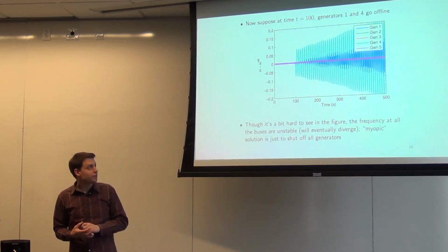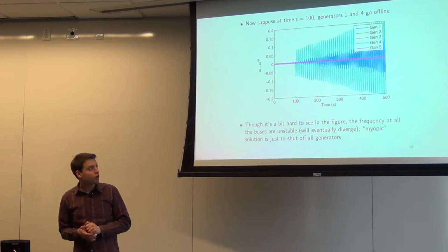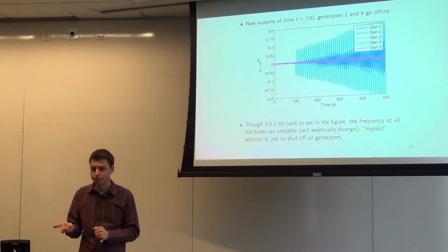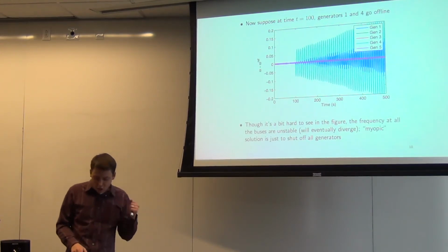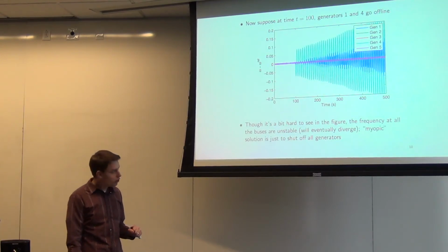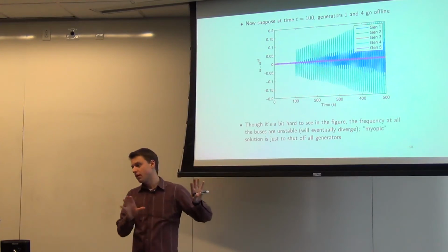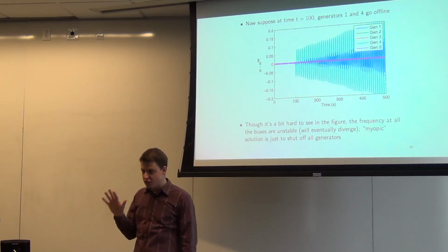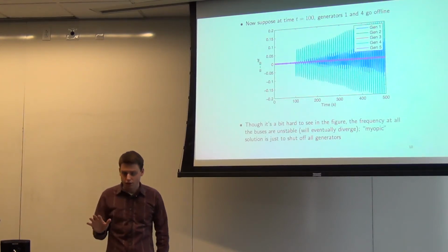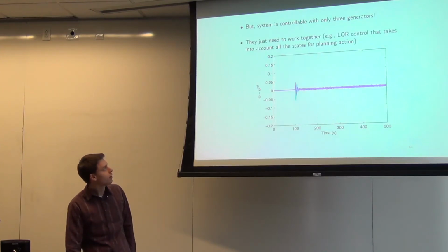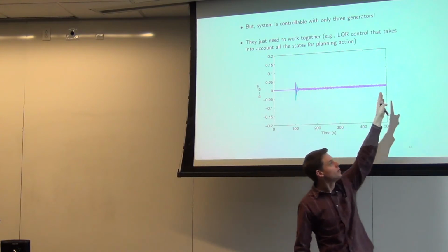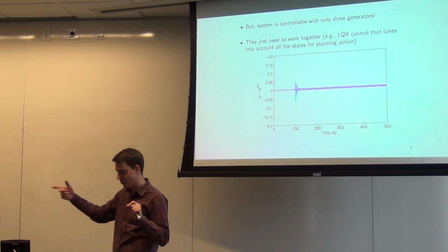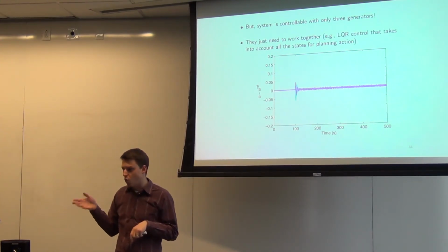Now, the interesting thing here, and again, this is all generators independently executing that PI control loop to regulate frequency, is that there's no need for this to happen. If you look at the system as a dynamical system and think about only 3 generators being there instead of 5, this system is still perfectly controllable. You can actually guarantee that every node in the system has 0 deviation, or on average 0, from the reference velocity, while only using 3 generators.